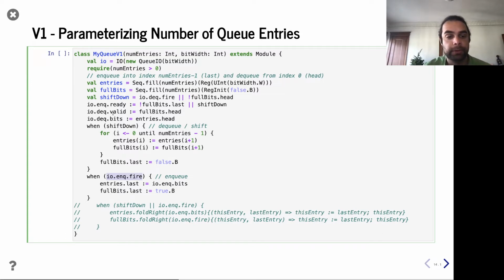We control .ready, and so of course that's required as room, right? And just like the prior one, to get that pipeline behavior, we're going to do the dequeue first and potentially enqueue and override it second. Even though I say first and second, think of this more as precedence, where we're giving the enqueue greater precedence. They're happening in the same cycle, right? You're never going to see that value glitch to 0 or something.